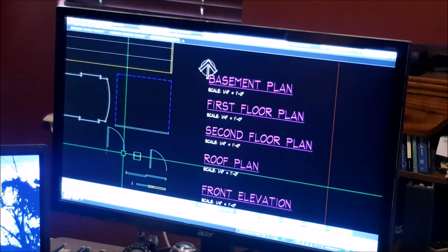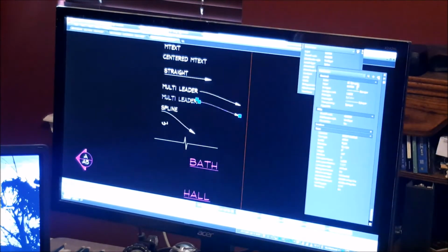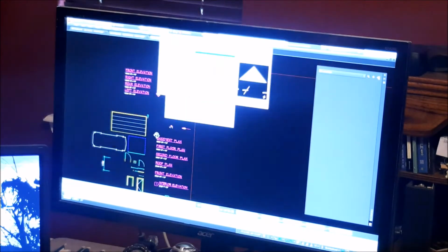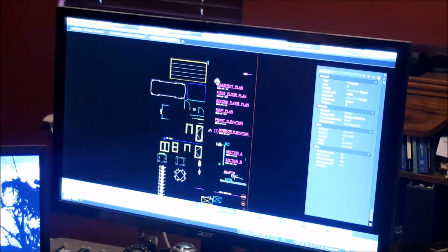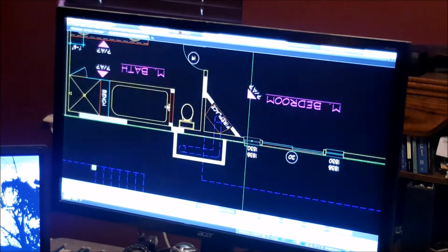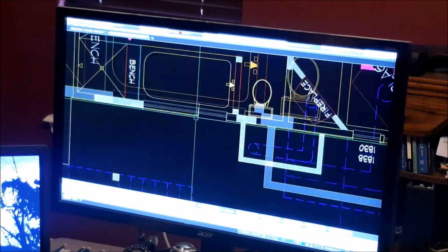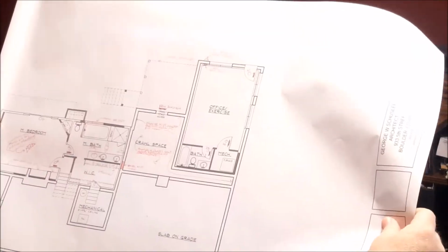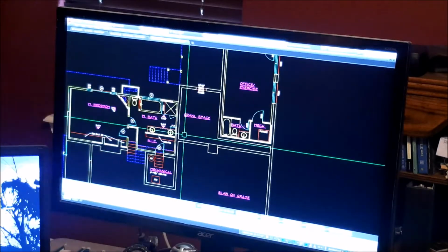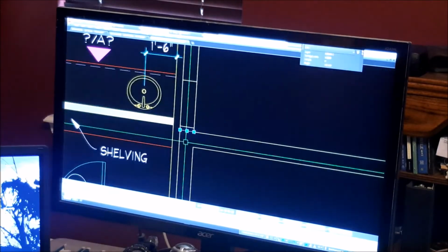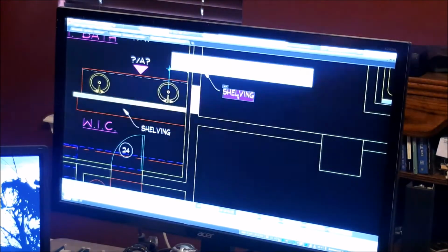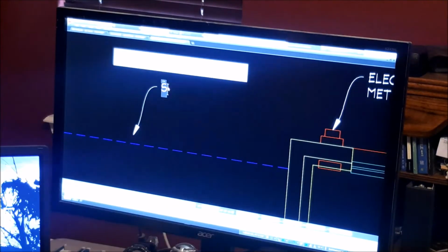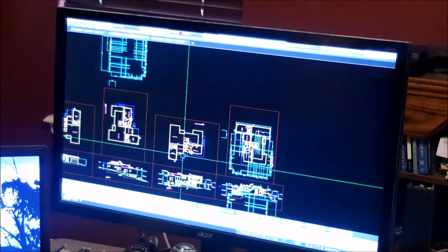I hope everybody knows about the Control key. The Control key in AutoCAD will save so much time. I don't know if you know this, but if you have a hatch, you can use the Control key to insert and remove vertices and even add a curve to a polyline of a hatch. I like to use it to keep a line straight. If I'm editing a line and I use a grip and hit the Control key, it will only go the direction of that line. It won't swing out and stretch it like it usually does.